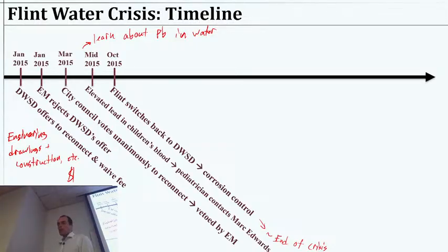We always want to operate, and maybe I mentioned this before, but we want to operate our distribution systems in a way where instead of corroding away material, we are slowly adding material. So if you've ever had hard water and you see mineral deposits kind of gunking up your sink or your shower or whatever, we want that to slowly constrict our pipes until we have to replace them, instead of the opposite, which would be just taking away materials very slowly, but water will eventually erode things, right? Even if it's a very, very small amount dissolving, over many years, you will eventually dissolve the pipe if you're heading in that direction.